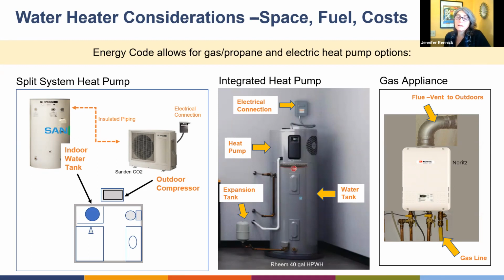And they do come with duct kits where that kit will either pull air through a louvers on a door, or pull air through a duct and then extract the heat out of that air. Even if the air is cold, there's still heat to be gotten. Can extract the heat out of that air and then exhaust slightly colder air out and to the outdoors.